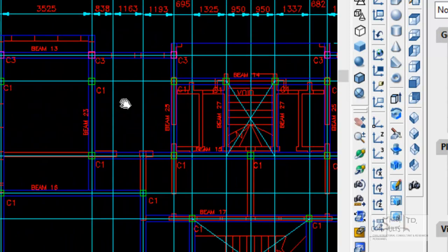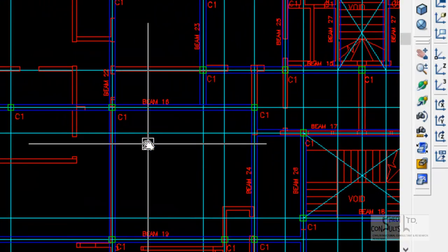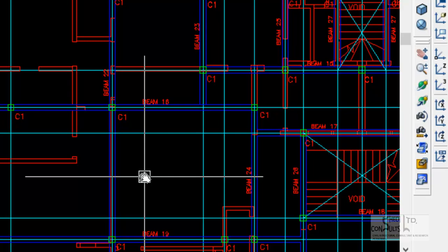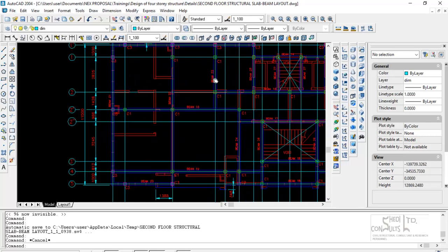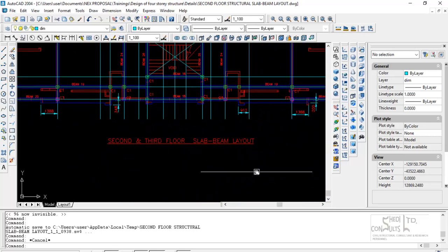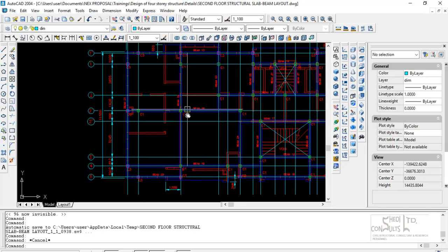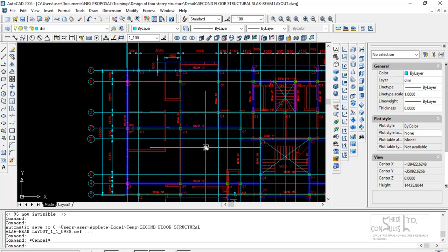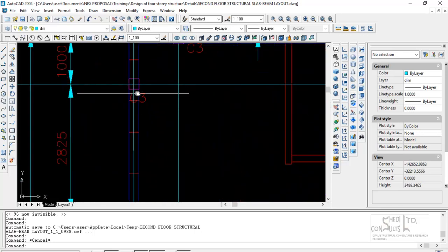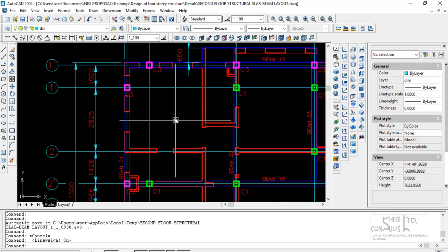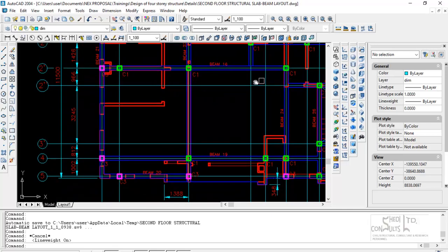So use a similar grading system as you have on the architectural design, so that it can easily be referenced back to, and then you have a proper synergy and an alignment in structural design. So this is the first floor. So this is the second and third floor structural layout, right? So what we showed initially was the first floor structural layout, which had a cantilever. Second and third floor is typical. Architectural layout is typical. Structural design for those floors are similar. So you would see the columns that start from the first floor. You see them going up there. So you develop your structural framing properly. So you have your structural beams.